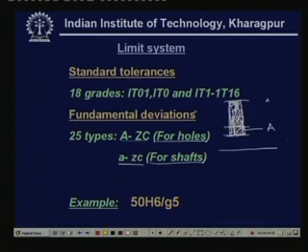You are having a fundamental deviation which is of the category A. However, for A, its tolerance in manufacturing could be IT1 suppose this much, IT10 suppose this much, IT16 suppose this much. Well, IT10 means starting from here, I am sorry, not from here. This is an IT10 say.